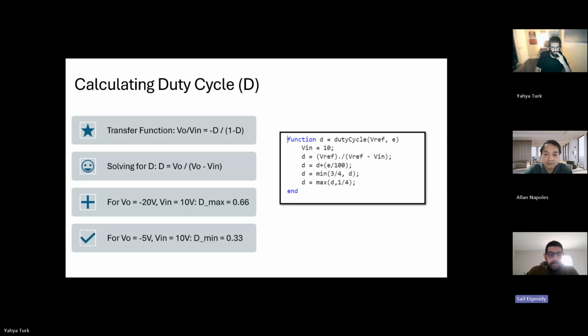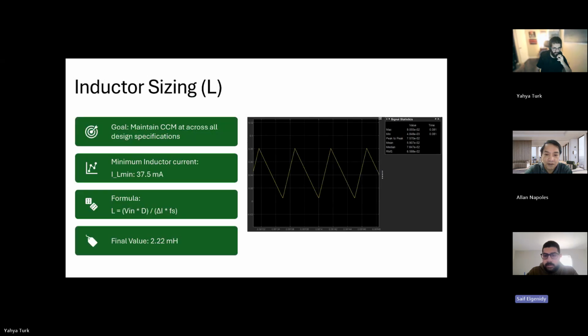And the converter is designed to operate in continuous conduction mode, which means the current never drops to zero, as we can see here. The current increases and then decreases without touching zero, and this is important to guarantee system stability and allow more predictable control. The first method is the standard PI controller.